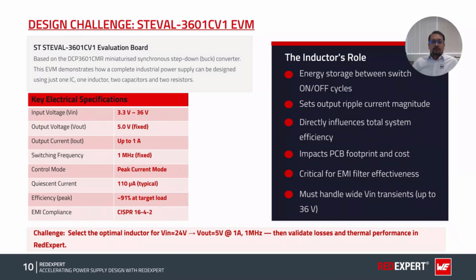As you all know, the inductor plays a critical role here. So finding an optimal inductor is definitely a challenge, because the inductor sets the output ripple current that directly influences total system efficiency, also impacts PCB footprint and cost, and it is also critical for EMI filter effectiveness. So let's dive into this and find an optimal inductor for this particular design.